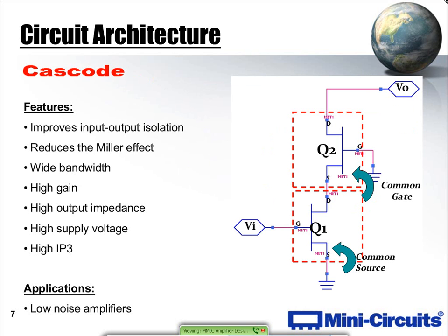The cascode approach, on the other hand, is the approach that's giving us the lowest noise designs. This is one that's giving us the 0.18 dBs. This is the design that has a very high intrinsic gain built into it, and because of the nature between Q1 and Q2, there's actually a very low impedance between the two transistors.